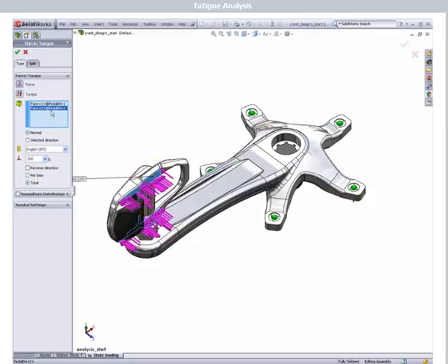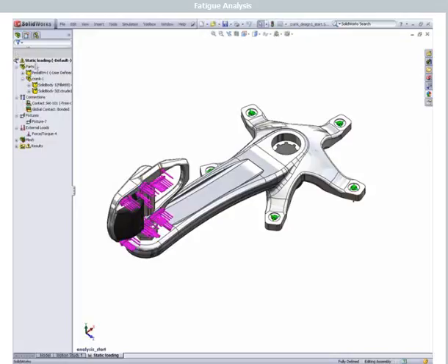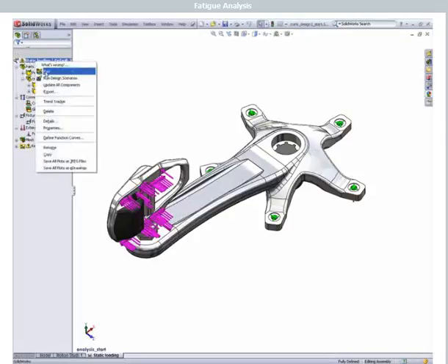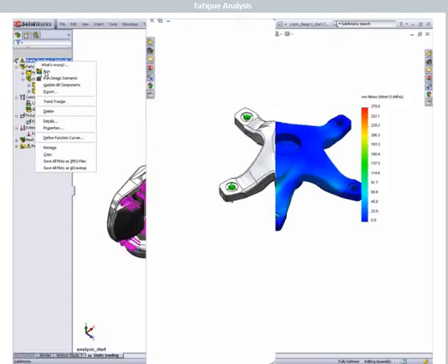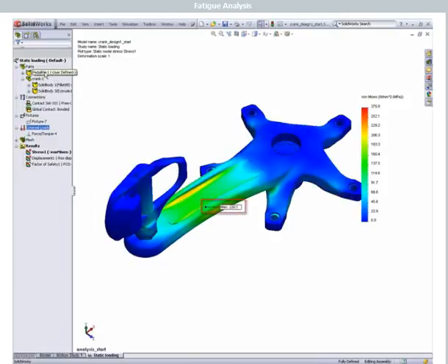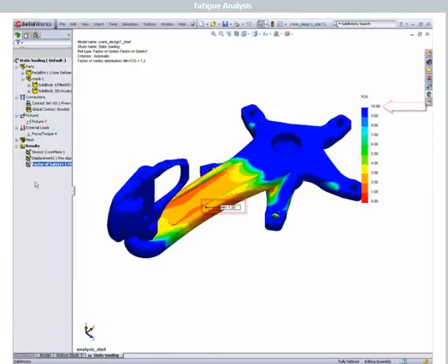It only takes a matter of seconds for SOLIDWORKS Simulation to calculate the results. We can see here the maximum stress in the model is 230 MPa. This is well below the 275 MPa material yield. This leads to the factor of safety of around 1.2.